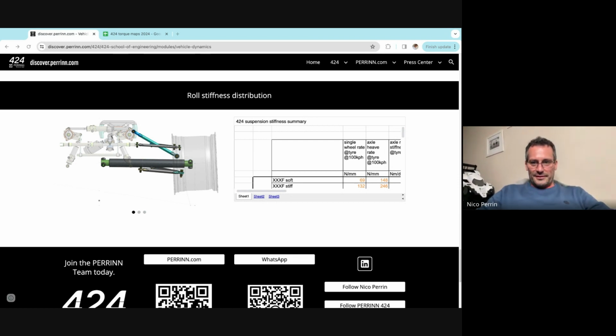Okay, we are back. Much better. So I haven't spoken about suspension yet, only because I wanted you today to understand that for this type of car, it's very much like F1. It's aerodynamics, power distribution, weight distribution before suspension. And that's why in F1, they only talk about aerodynamics or development. You can see the suspension is compromised versus the aerodynamics because it's more powerful for this type of car.